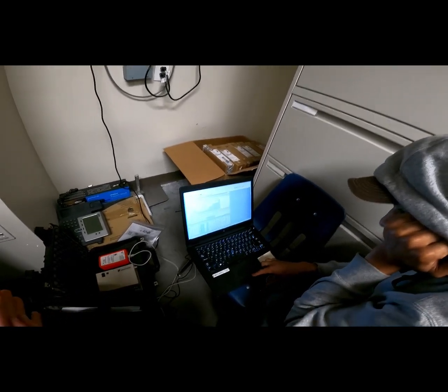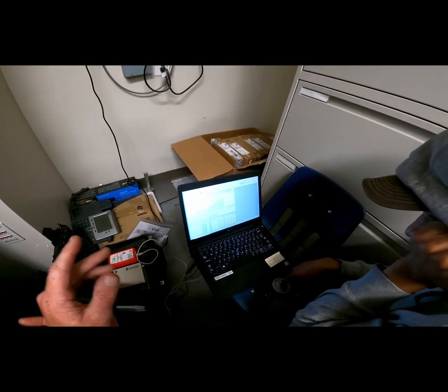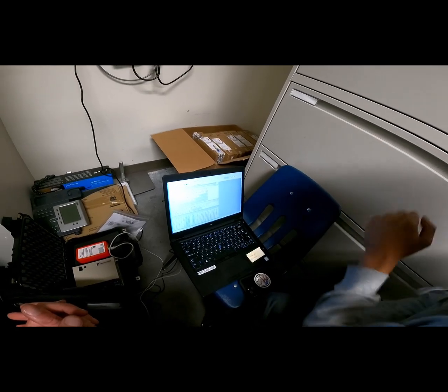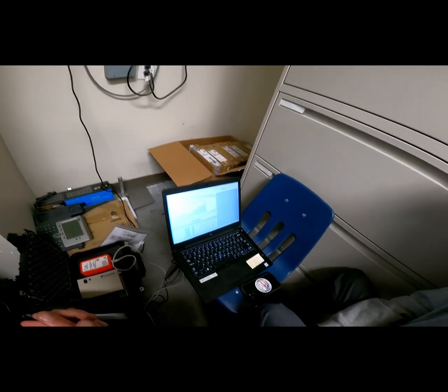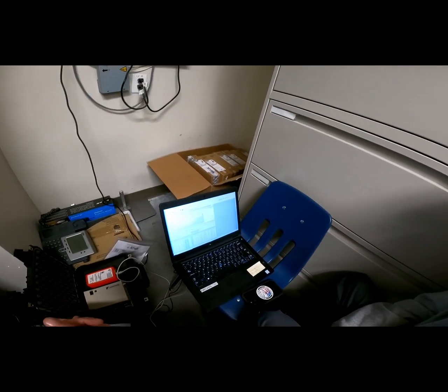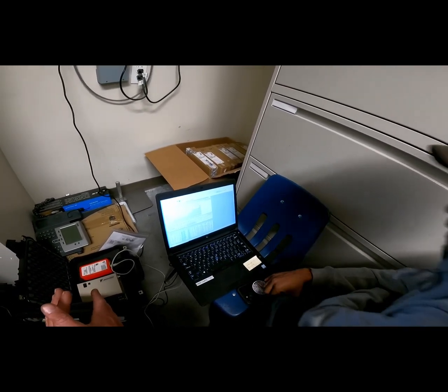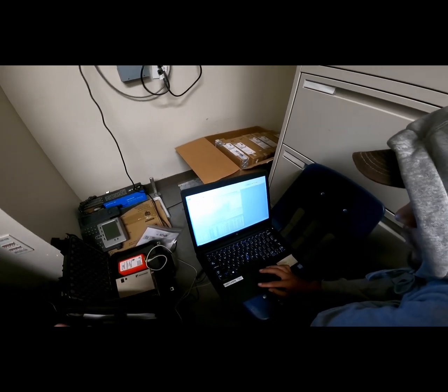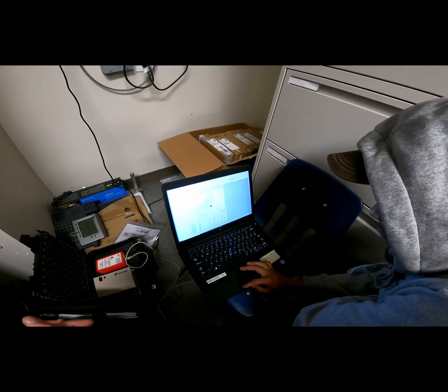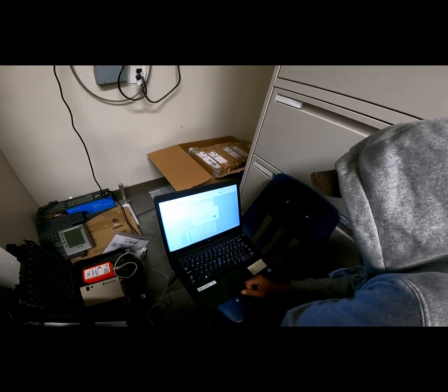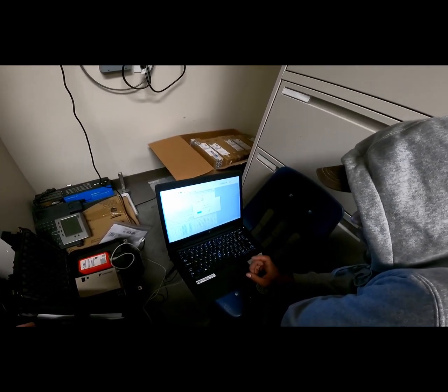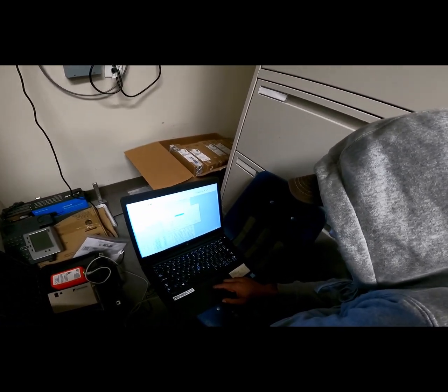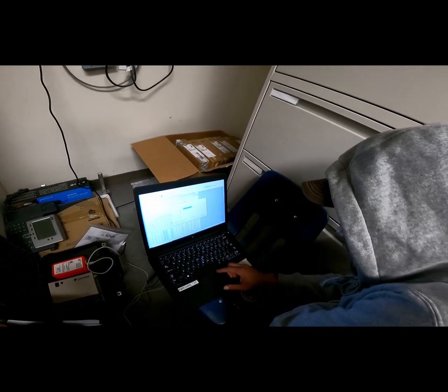Now here's another important thing. You're still monitoring that one outdoor unit and all of its indoor units, right? Unmonitor it. Well, we're going to jump out. We're in monitor mode right now. We performed a test while in monitor mode, but we're going to hit return right here, and you're going to finish the status monitor, and it's going to ask you if you want to save the information. You definitely want to save the information, because if there was something funky going on, then I can go back in the offline mode and analyze the data.